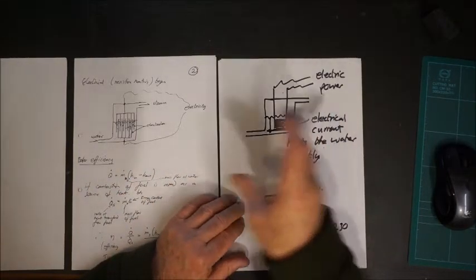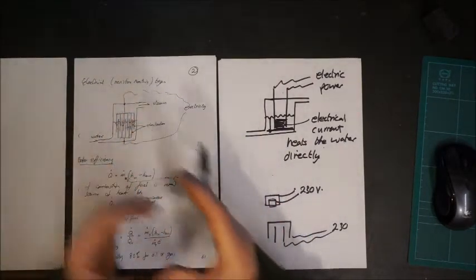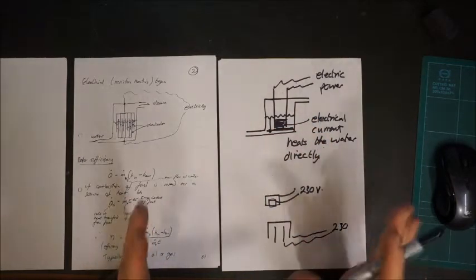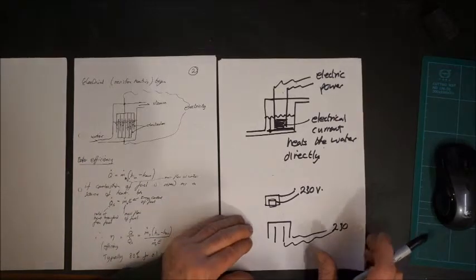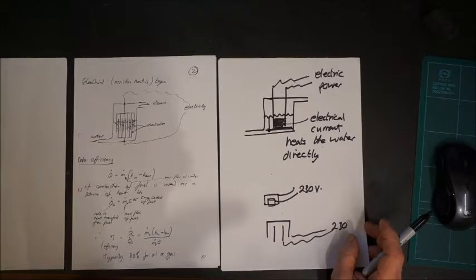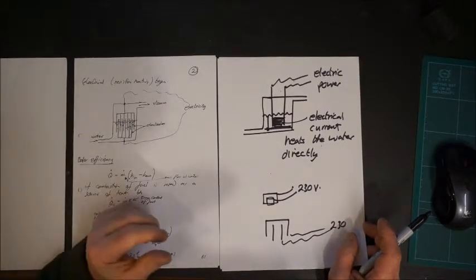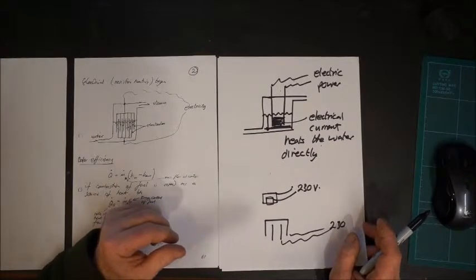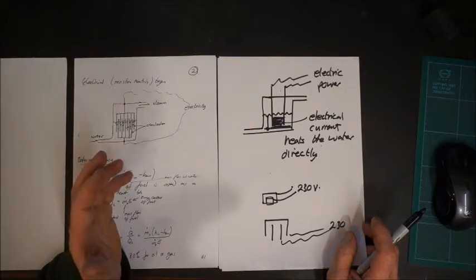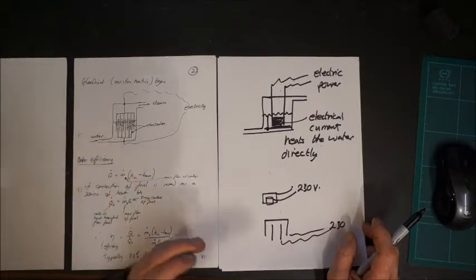And because there's no tubes, there's nothing other than just a box with a lot of electrodes in, they're very simple, they can be very cheap. And the big ones can actually generate a lot of power. I've seen one almost the size of this building. This was in Canada, and it was used to provide a huge amount of steam for a paper mill. And it really was quite simply a series of huge boxes plugged directly into the very high voltage power coming directly from the northern Quebec power stations. Very effective.